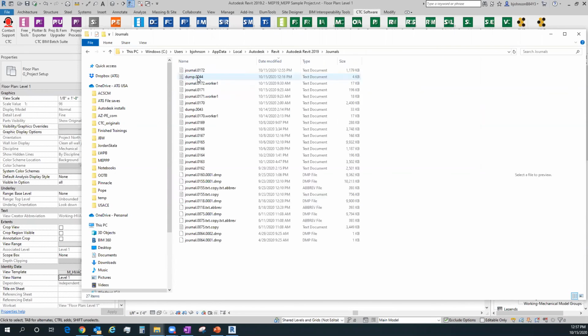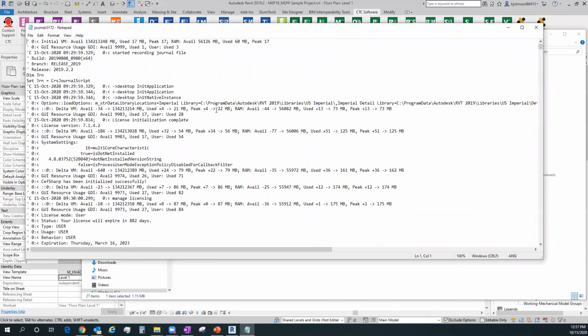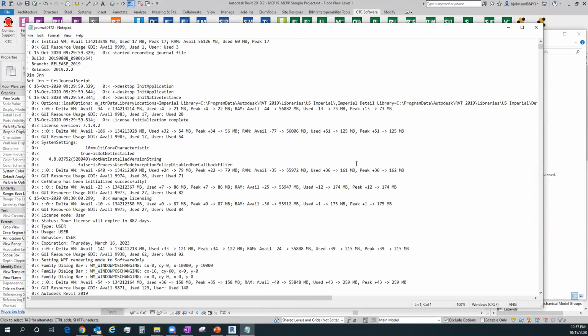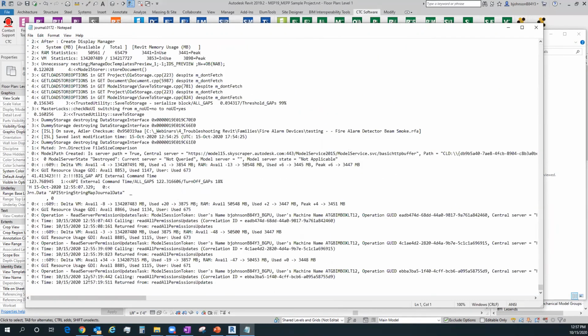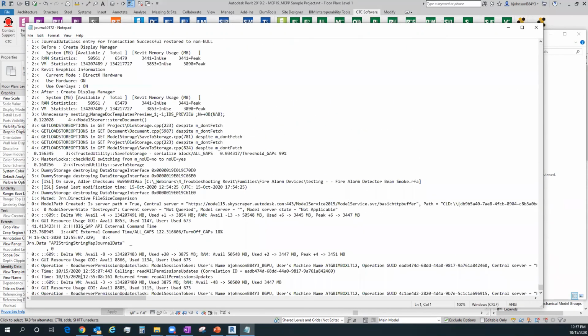So if I go to my journals folder and look at my journal documents, here I've got my 1015, that's today, it's 1257 right now, the last write was 1255. These are live text files. So as you continue to work in it, it's continually adding stuff to it, even if you open it with a text editor. So within the journal files, if I've crashed and I'm the end user and my machine was the one that just crashed, I almost always go straight to the bottom and then I read backwards. So I read through some of the things that are actually going on here. And there's a lot of garbage in here, so it's not something that's easy to read through, right?